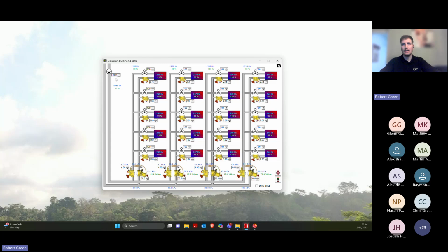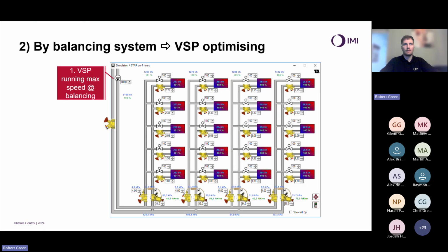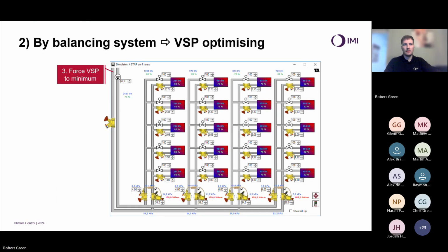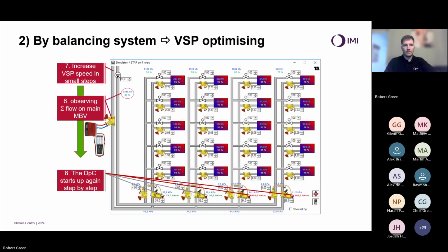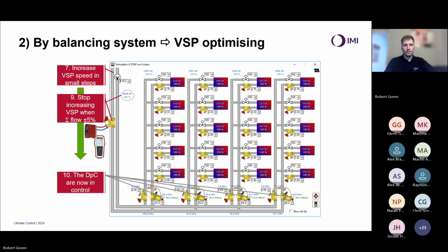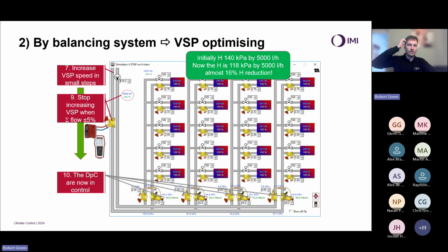So we can now say we've optimized the setting of that pump, and we've now absorbed all of the excess differential pressure in these valves. And we can now say we are fully in control. At 100%, we've optimized those pumps. So it's a fairly simple procedure, but it's a vital procedure. And in my experience, it is a procedure that is not often carried out.